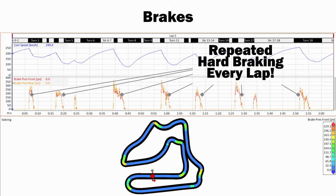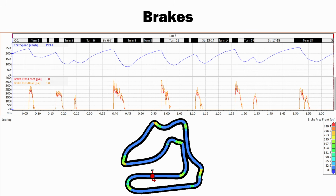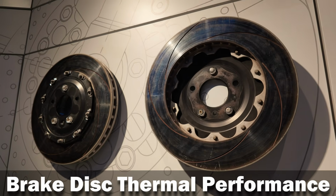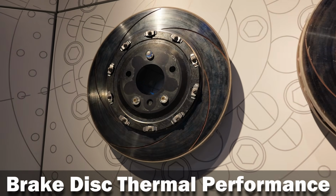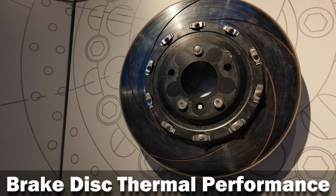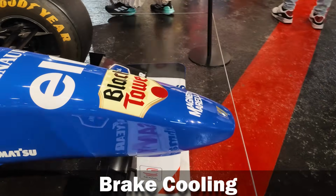It means the brake pads that you're going to use are going to have to be designed to give good friction at high temperatures, rather than on the roads where we might want brake pads that give you good friction from a low temperature. It also means that our fluid needs to withstand much higher temperatures before boiling, and we need to think about the amount of material and size of our brake discs to ensure they have decent thermal capacity. We also need to think about cooling for our braking system.